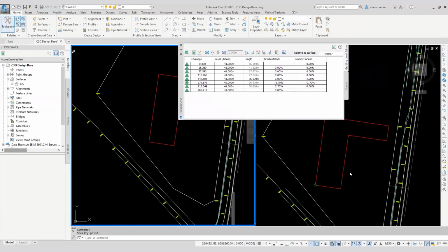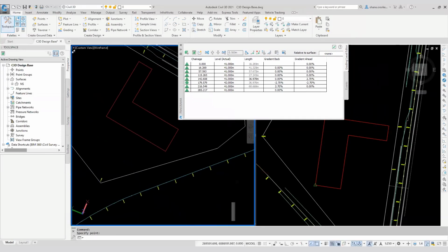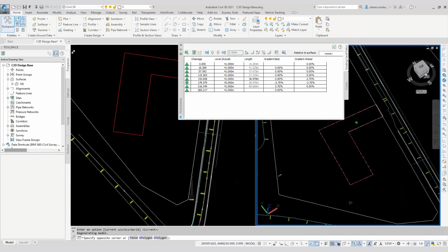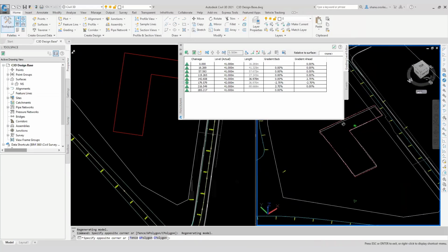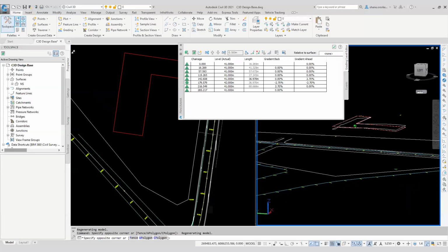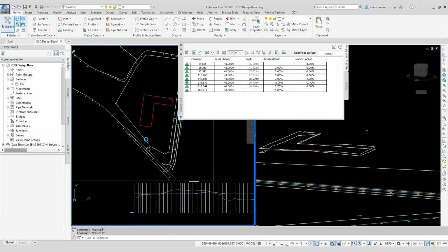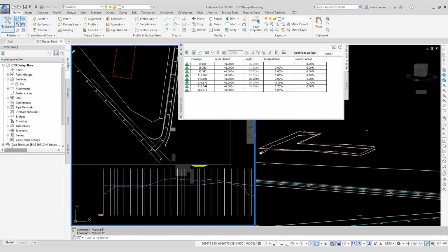And if I just make this 3D again, we'll sort of be able to see, I'm making the wrong one 3D. If I make this view here 3D, we can track there that there's a ridge happening in here. Okay, I think the reason you're seeing this other line is because of the quick profile. So because the quick profile is making basically a profile around that edge, that's the existing ground you're looking at there. Okay, so with that elevation point, it's actually defined quite nicely in the panorama.